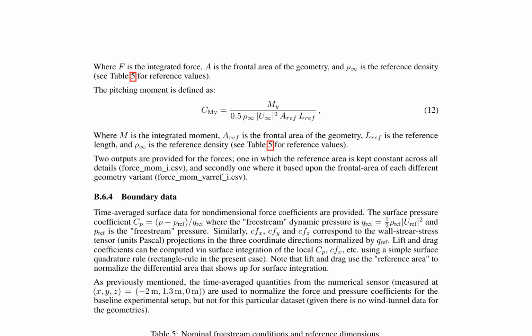Pitching moment is also defined, utilizing the integrated moment M, frontal area RF, reference length LREF, and reference density ρ infinity. Outputs provided for the forces include one with a constant reference area across all details and another where the reference area is based on the frontal area of each geometry variant.